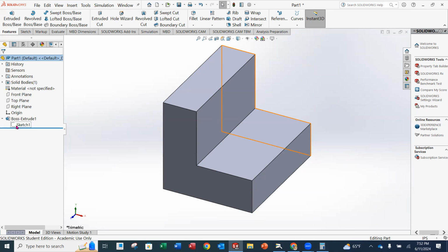When you do your screenshots for me and hand them in, I want these expanded out, because I will know everything was fully defined as long as I don't see a parenthesis with a minus in front of your sketch. When there's nothing in front of it, that means it was fully defined. I don't need the file to do that. I just need to see that.